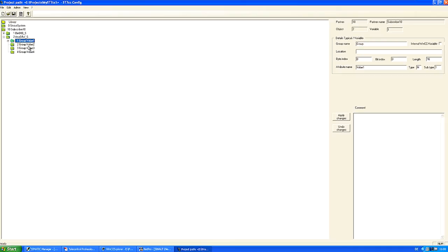To do so, we select a parameter block and specify the raw value and its physical limits. We receive a raw value from the SIMATIC in a range from 0 to 27,000. This should be converted to a physical value, for example from 0 to 100 centigrade. With an archive block, the analog value is automatically copied in the selected WinCC tag logging archive.